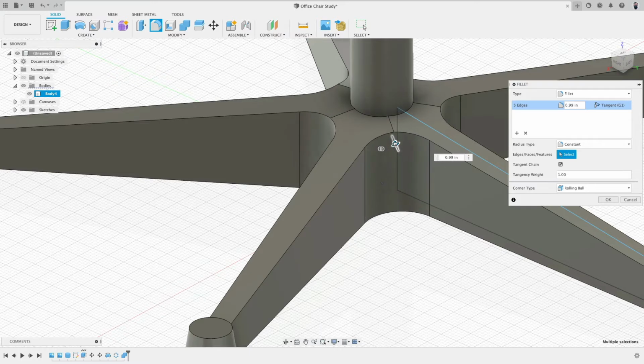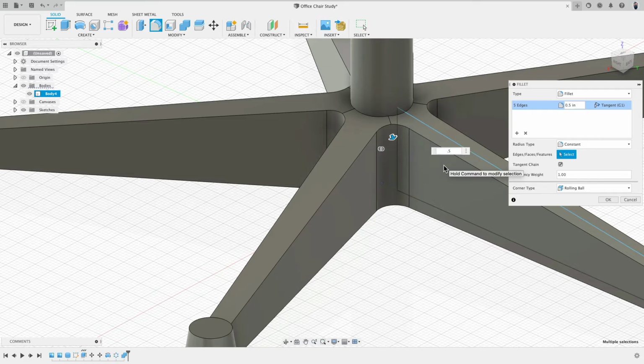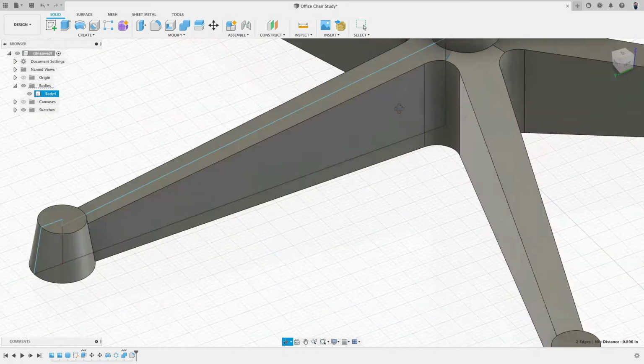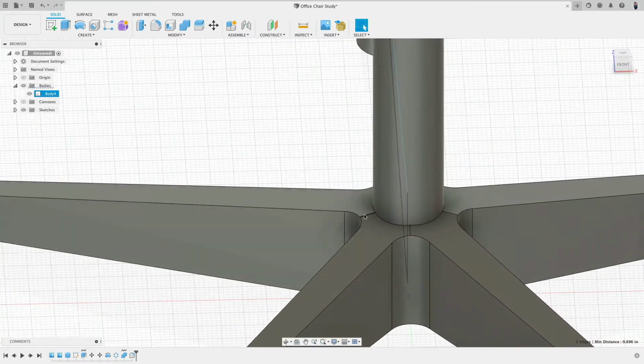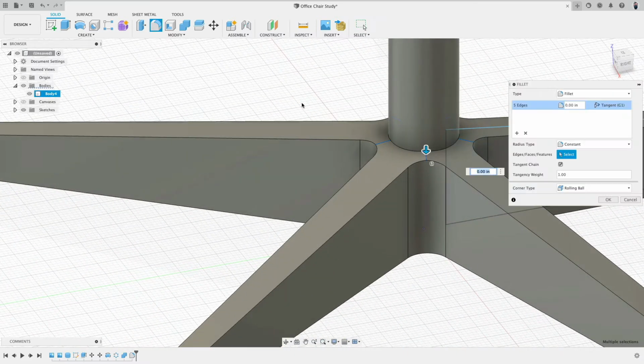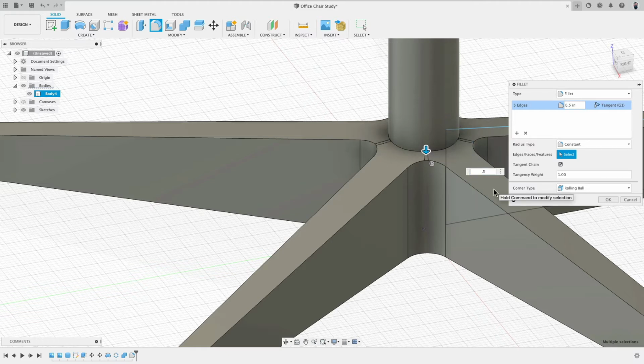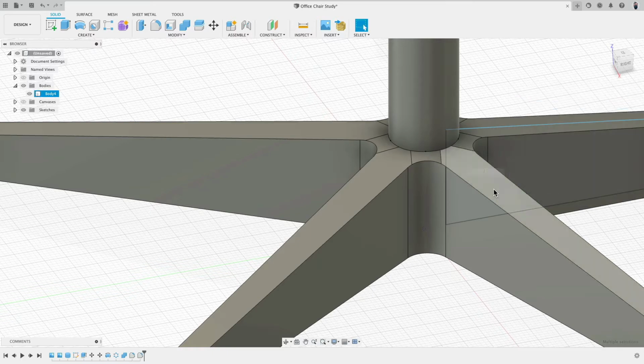create myself a nice base, 1 inch, 0.5. Yeah, 0.5 feels better. It's not too big. Then in the second pass, since I'm working at the center, I will select all these edges and round those. Let's see by how much, 0.5. Oh, it was 5. Okay. Or 4. Very good.